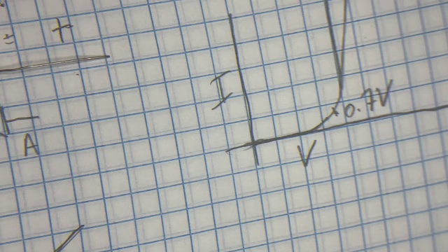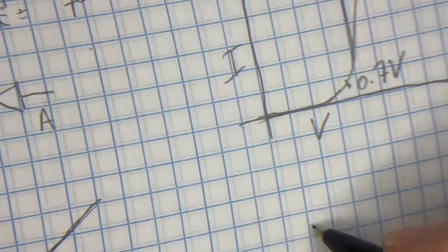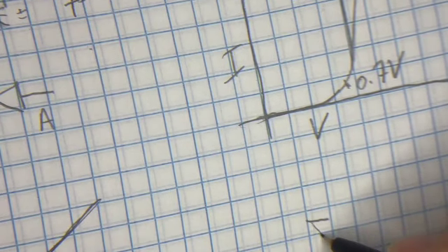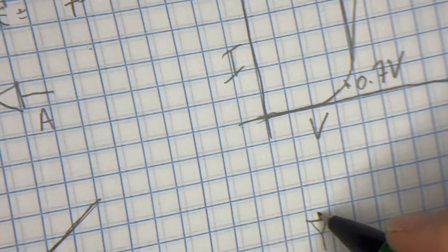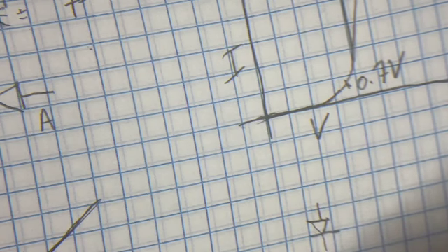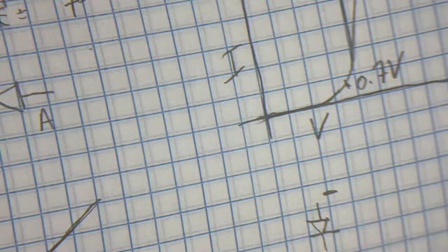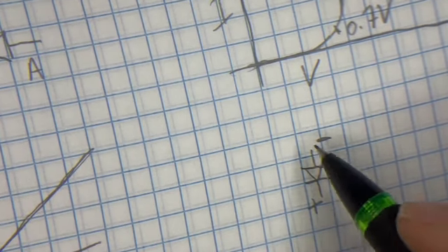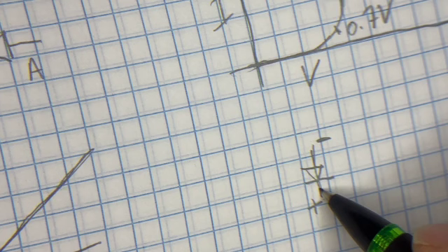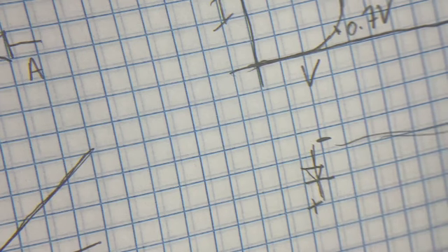Like, for example, you may see on a schematic a diode going like this, with the positive voltage here and negative voltage here. The whole idea is that if you put the wrong polarity on there, the current will flow through this diode, protecting the rest of the circuit downstream from any reverse voltage damage that could occur.